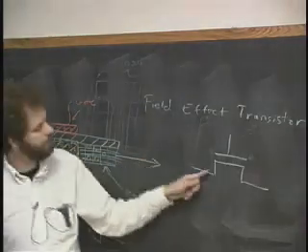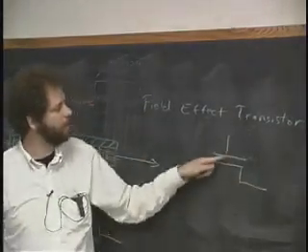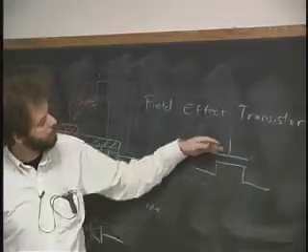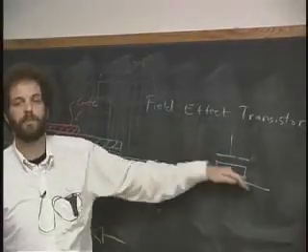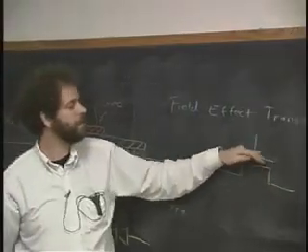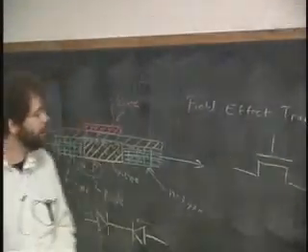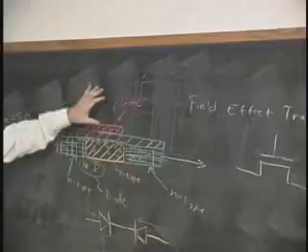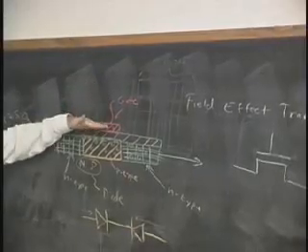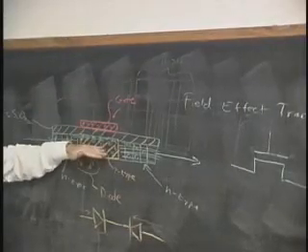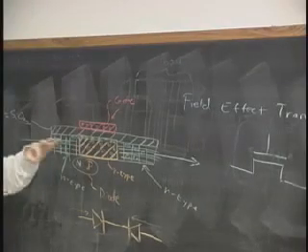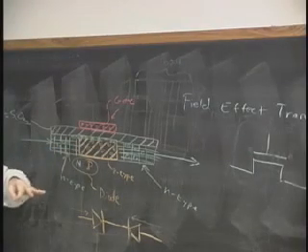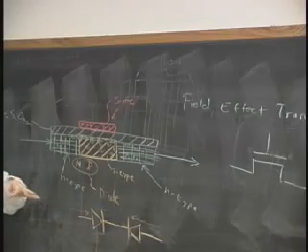Okay, where that exactly corresponds to the 3 terminals that I've drawn here. We're trying to get current through this path here, and it's controlled by this gate. And notice the space between the gate and the channel that we're trying to get the charge through. That space is where the insulator is, and that's to indicate that I charge and discharge there, but this gate doesn't really physically interact with any of the circuit down here. It only opens and closes the gate, just like a person that opens and closes the gate but doesn't interact with the people that flow through.